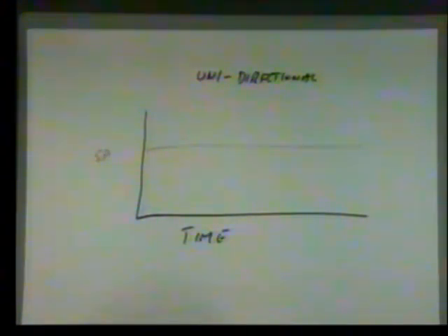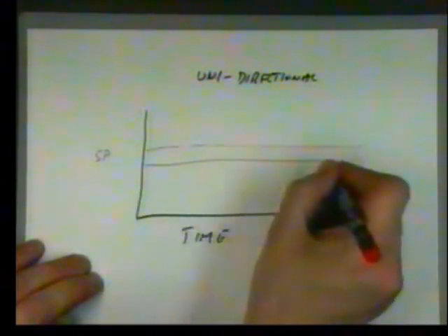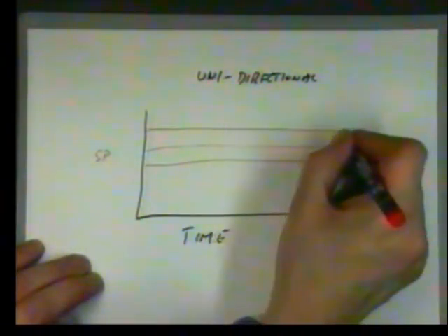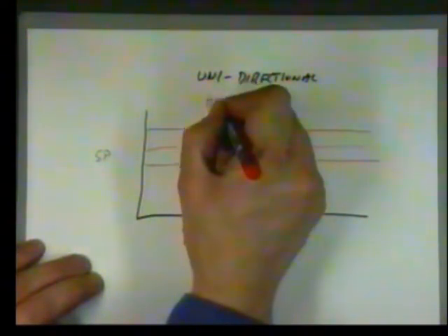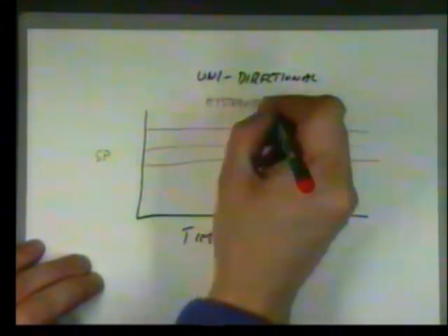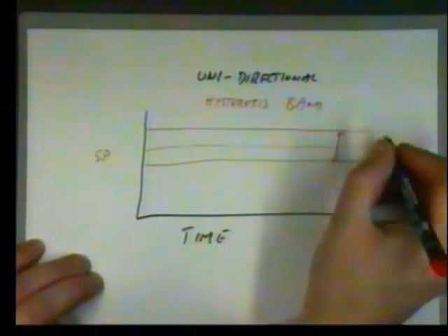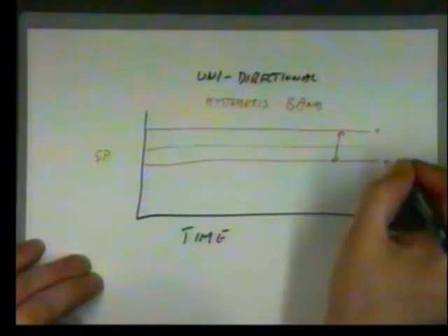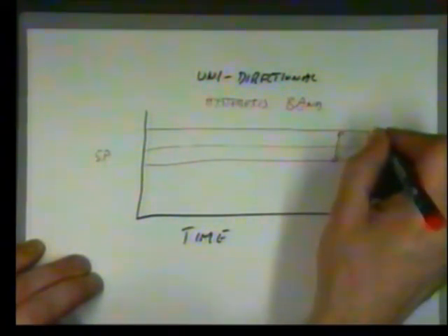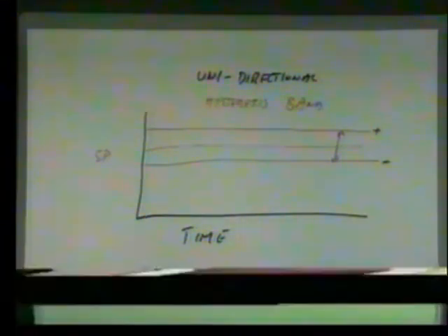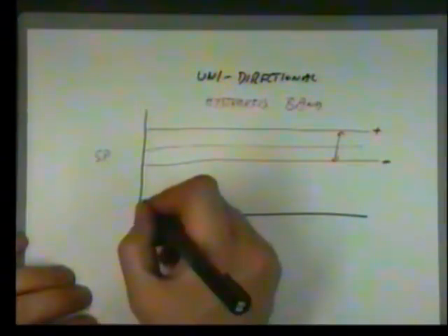So instead what we do is we broaden, we spread out the set point into what is known as a hysteresis band. We actually widen it. In fact, what we have is a plus and a minus hysteresis. And the way it works is that instead of stopping driving at the set point, we deliberately pull it through to the upper end of the hysteresis band.